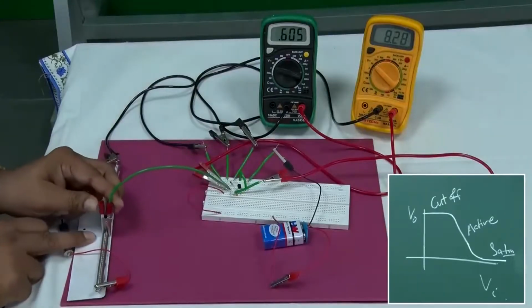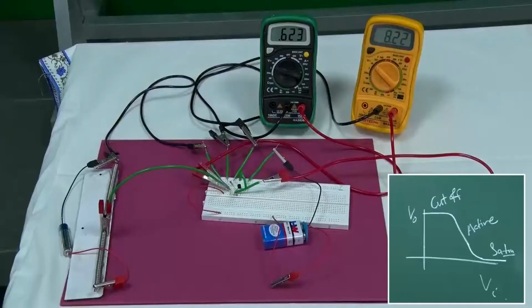Again, increase it further. If I increase it further, what happens? See, the input voltage is now 0.622 volts. Remember, after that you have 120 kilo ohm of resistance, there is a current IB there, there is a drop on this 120 kilo ohm. So, what reaches base will be a fraction of voltage, 0.2, 0.3, 0.15 type volts.